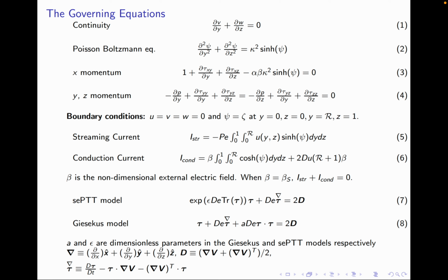Now, two types of electric currents flow in the liquid. First is the streaming current. When charges flow along with the fluid, it amounts to an electric current called the streaming current. Now, if an electric field is present across the channel, it leads to conduction. If no electric field is present, the total current should be zero, right?